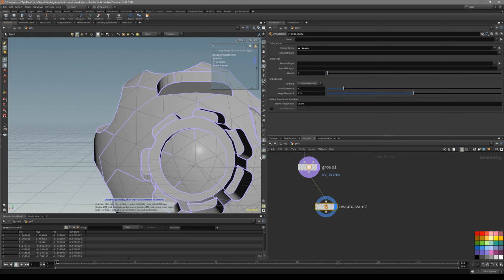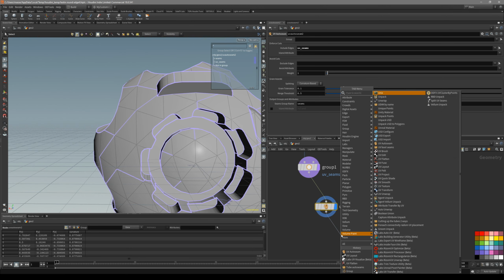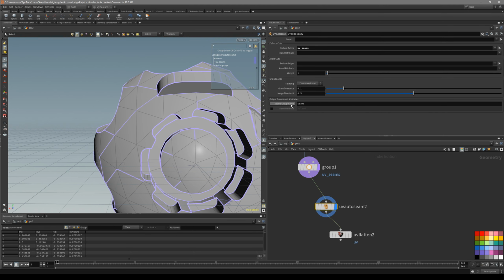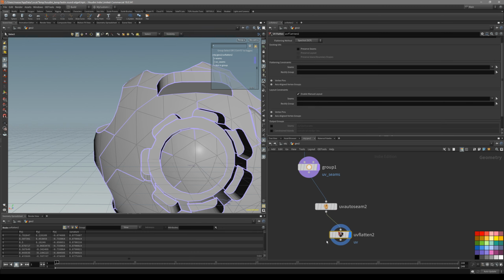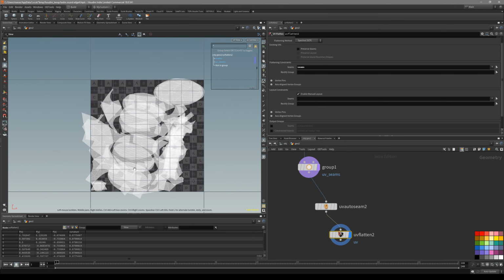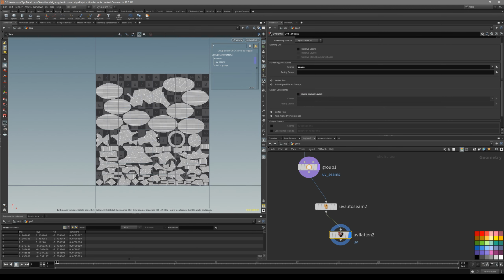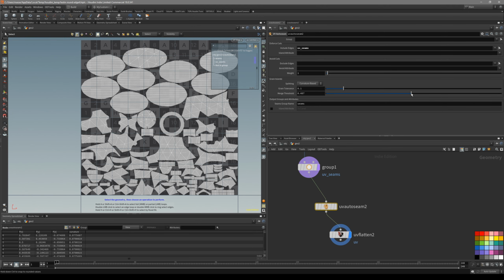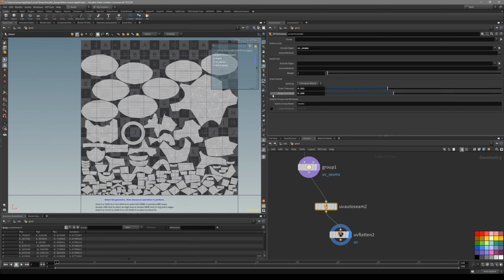So what I like to do is actually go to UV flatten node. And since UV seam is automatically going to output our seams, all we have to do is in UV flatten seams, group seams, like that. What I like to do is go inside our UV layout viewport and disable manual layout, like that. And now all you have to do is go back to UV seams and start playing around with this gain tolerance and merge threshold.